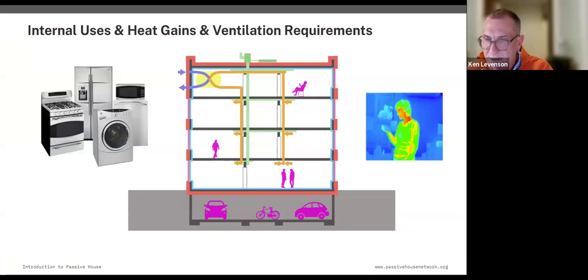Is it better for the ERV or HRV to be inside or outside of the building? Well, typically in a smaller residential building, it's going to be inside. Bigger commercial buildings, it's often outside, but it could be inside. It could be either way. In a single family home, I've seen retrofits in the Netherlands where they're kind of outside because of the way they did it. But basically, 99.9% of the time they're always within the home. They're in the utility closet, in the laundry room somehow, hopefully near the exterior wall.